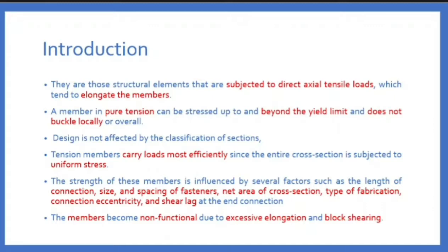Can you see that you have done a UTM test? In that you place a steel member. How have you tested that steel member? Either you have tensioned or compressed. You have tensioned. Note that when you are finding the behavior of the material of the member, you are tensioning. Why? Because under tension, you will know the pure yield capacity. You can do the same test by using compression, since in a UTM machine you can also compress. But the material will not take the 100% yield load before failure. That is why the tension test is done for finding the load carrying capacity of the member.